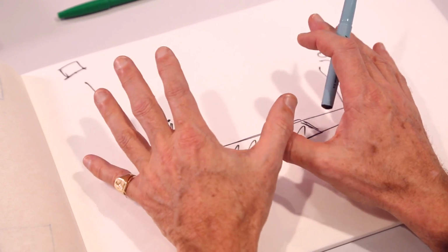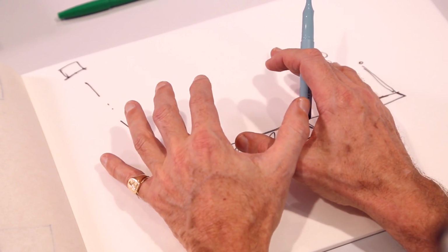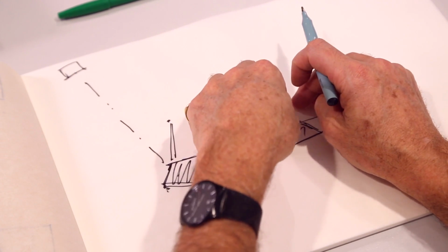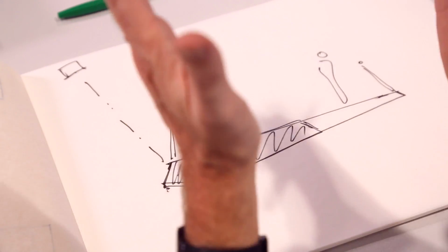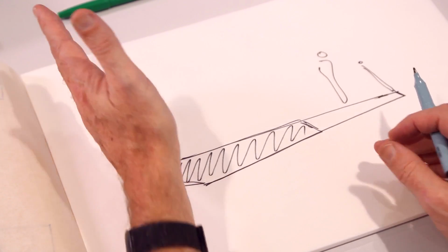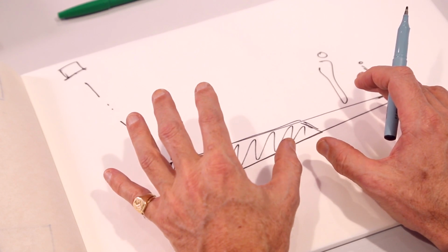But the purpose of saying that is that this again is another illustration of how the cross-section, the long section and the plan all have to be taken into account together. Where is the longitudinal support? In this case it's the arch, and how does the cross-section have to deal with that?